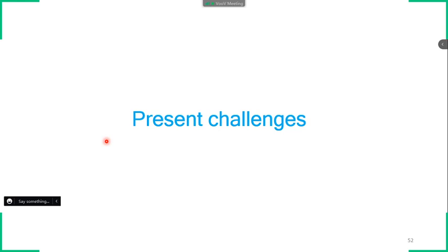Okay, fine then. Yeah, I understood your question. Actually, the substrate will be acting like a better heat sink, and you need not bother about how much it is going to get diluted. But for the first layer, it should have a proper dilution so that the first layer properly anchors with the substrate, so that when you lay a subsequent layer, your component won't get peeled out.